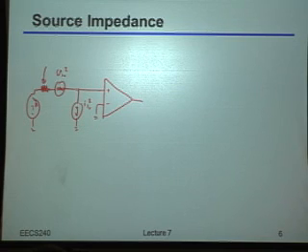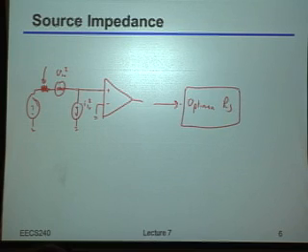Okay? So the real point here is that if you have a generic amplifier like this, it turns out there's an optimum source impedance to use. Okay? And by optimum, I mean source impedance that actually gives you the lowest possible noise. Now, things actually get a little bit complicated here. You can probably guess that if I really just had a broadband white voltage noise and a broadband white current noise, and they're totally independent of each other, you could very quickly figure out what the optimum impedance is. It would just be the ratio of the voltage to the current.